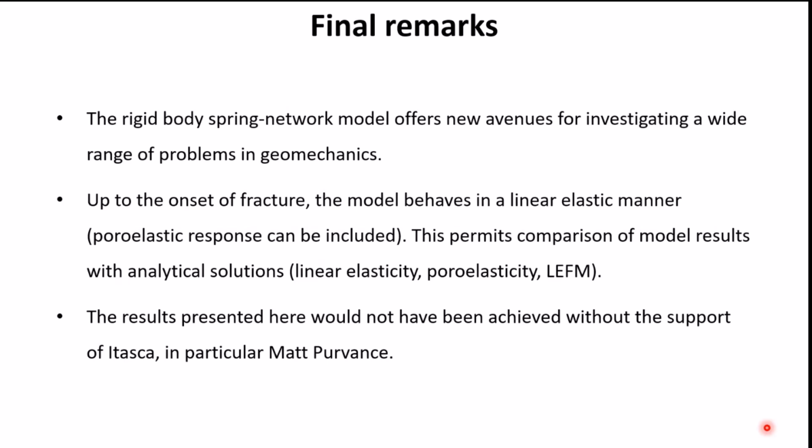It's crazy. I'm only doing rigid block modeling now for quite some time, because it offers really a new avenue for investigating a wide range of geomechanical problems. The neat thing about the spring network model is that you have a perfect linear elastic response up to the point of fracture. So this really nicely allows you to compare your models with analytical solutions, be it linear elasticity, poroelasticity, linear elastic fracture mechanics, etc.